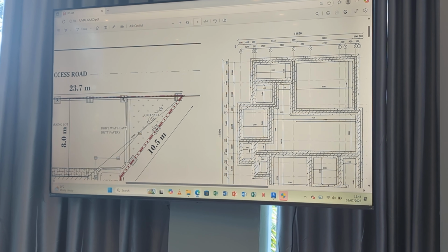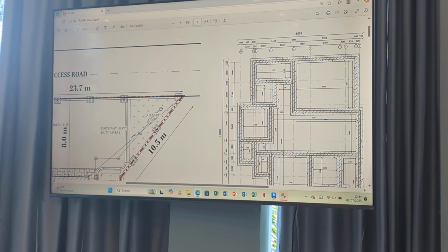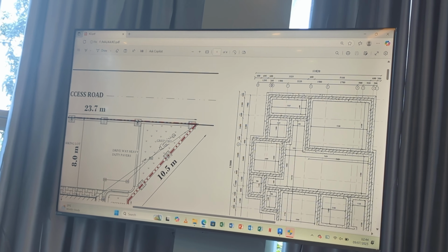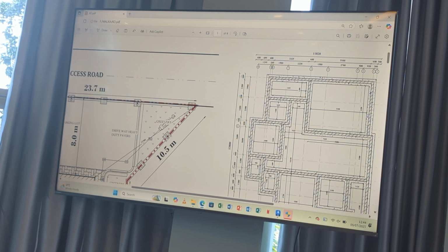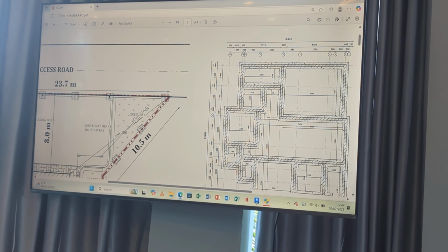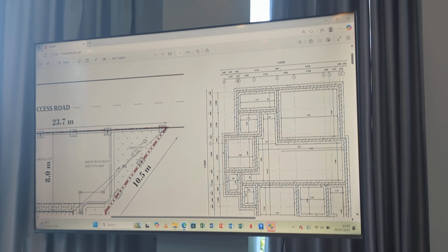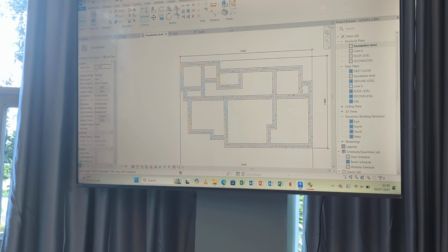But now since you're doing thicknesses, it's going to be 600. This time you're not looking at the wall, you're looking at the trench. This second one, you see that? Remember for walls we were doing 200, 200 because that was the thickness of the wall. For this it's going to be 600 and then the next distance to the next trench. And this will apply on all the sides. Then plus the internal dimensions, such that whoever is digging knows exactly that.